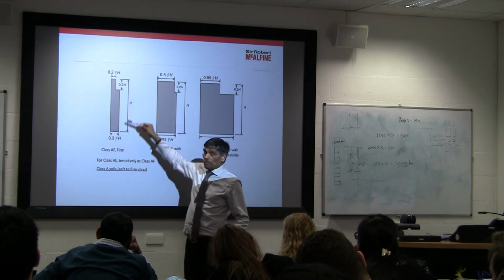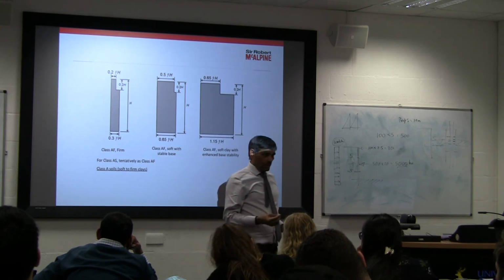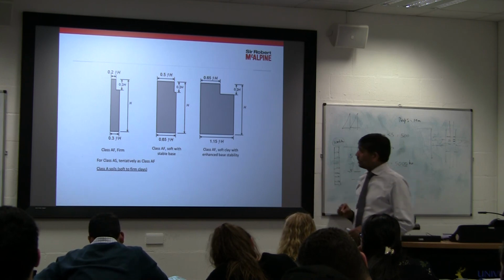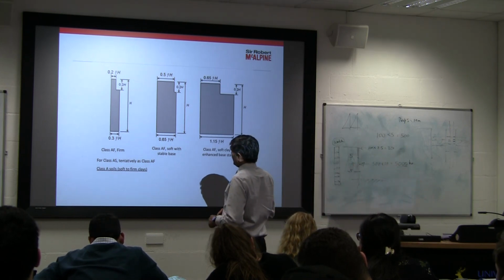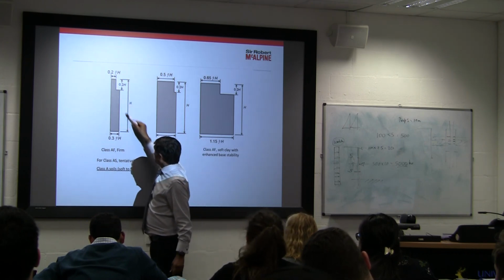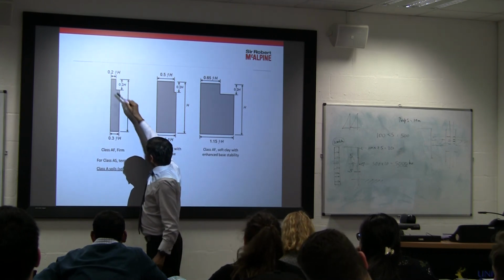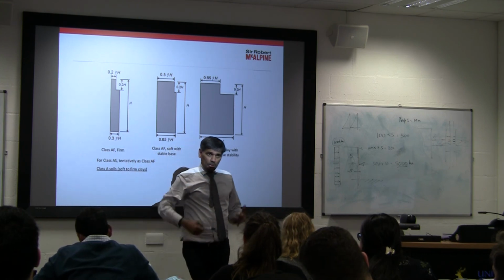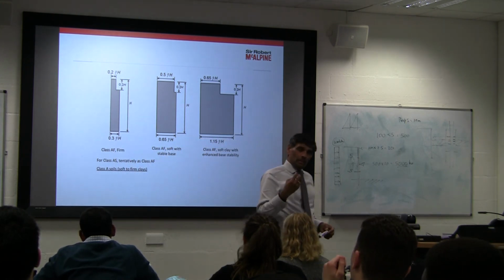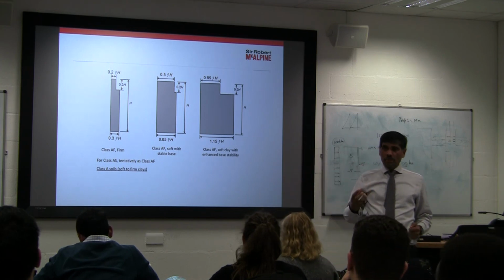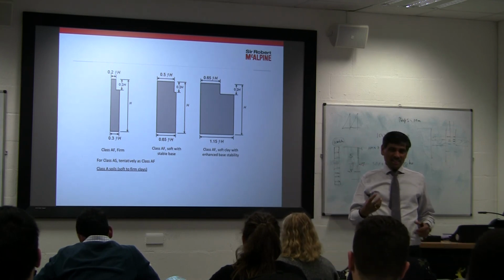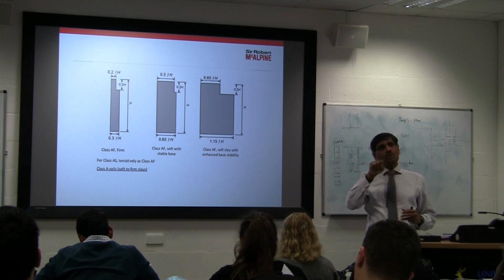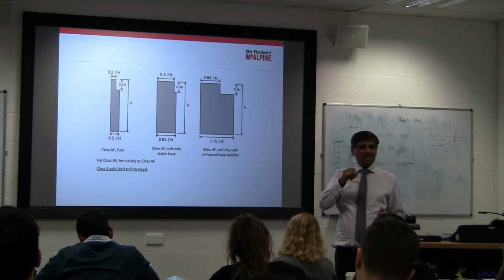So that's the pressure distribution at the back of the wall, which is idealized, which is the load that is pushed into the walls and the props. If you do a Rankine sort of scenario, you will say, okay, if it is H, I will put 0.3 gamma H, and you are overestimating your loads. But because the clay is heavily over-consolidated, to take the movement, you need to actually overcome what is the normal consolidation pressure. You are not reaching